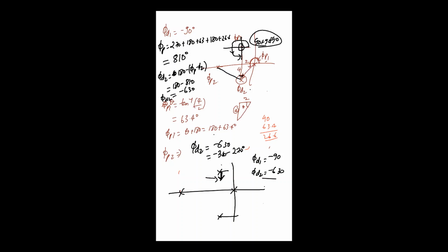This is the angle contributed by phi p2. So this is 90 degree, this is 180 degree, this is 270 degree. Yes, 270 plus. So what have I done? I have written it wrong. It can be 360 minus. You can do that also. If you want to calculate the whole angle, this is 360 degree minus this angle. This angle is 63.4. Yes, you can do that. Okay.